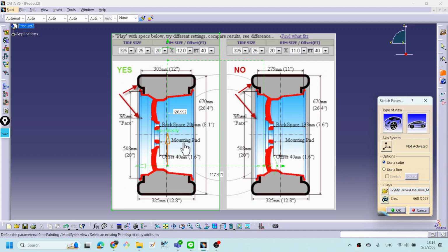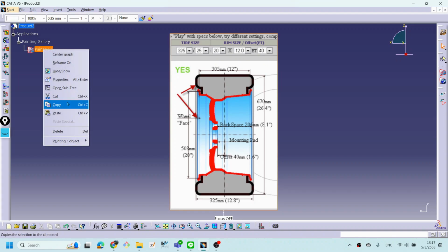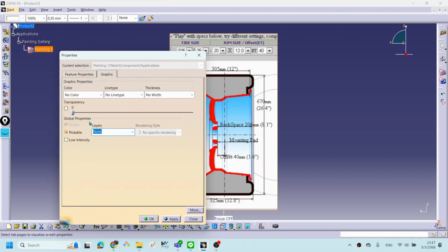Because it's not clear to look at the green color of the axis. Here our axis is not clear, because it's blending to the white color and harder to look at. Let me use the sum function. Adjust this picture first. Click the right button in your mouse, go to set up the graphic, click on the transparent, and set the transparent to around 120.